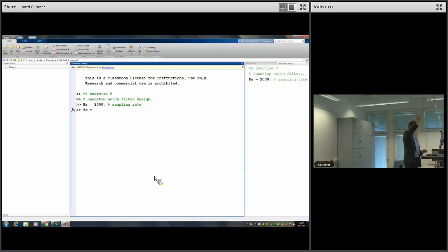Typical for transformers, you usually get the 100 Hertz signal as the highest or most energy in this line noise, AC line noise, because of the rectifier. Okay, 100 Hertz. Line humming.